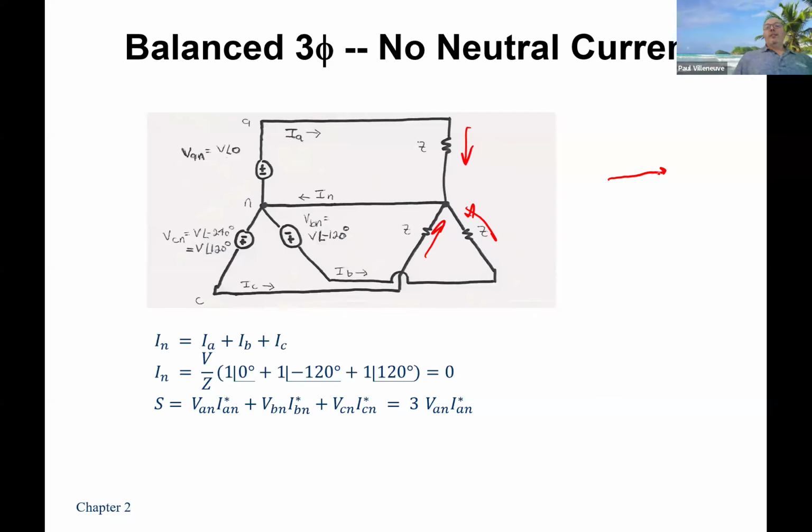The other current, we're going to add it to this, and the other current is going to add, and if I could draw, gets back to that point. So the currents going into this neutral circuit, when you sum them together, are equal to 0. In a perfectly balanced system, a neutral has no current, which means the neutral is 0 volts.